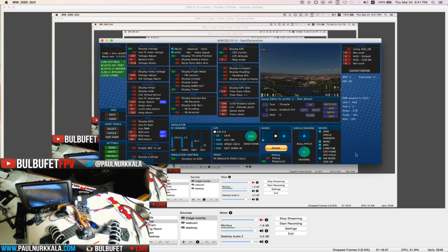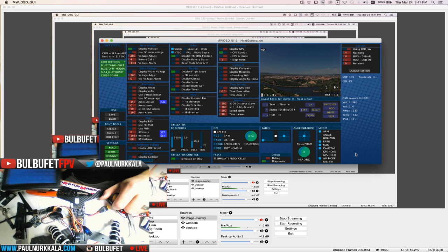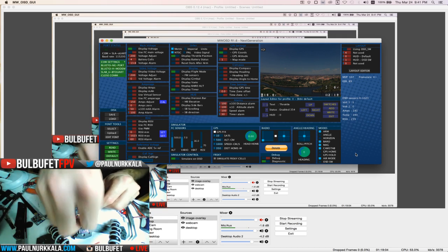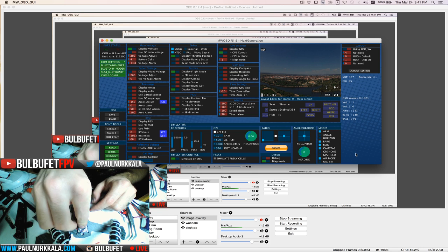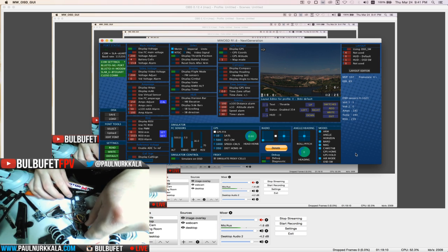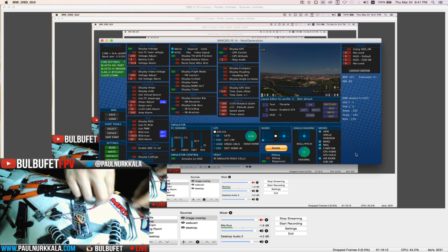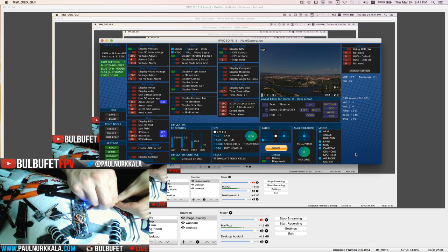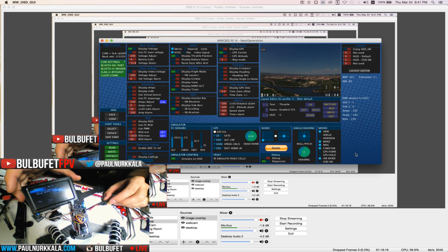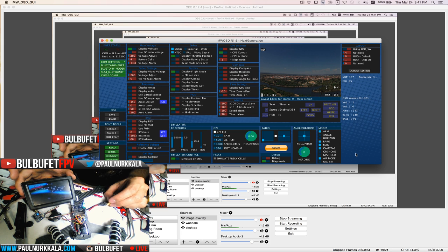We're going to power this down for a sec. And once again, we can just pull out the FTDI adapter, put in the one from the Dragonfly 32, power this bad boy back up, and voila, we're now connected to the OSD and flight controller, like that.